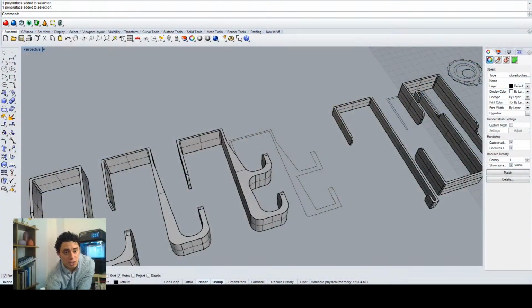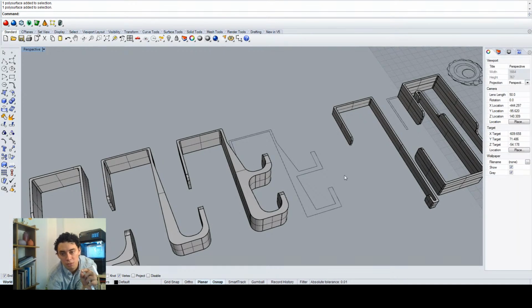So anyways, I started prototyping with it, saying how can I change this part? As I said, understanding what my requirements and my constraints were, and keeping that same door thickness constant, but allowing myself a little bit more beef, a little bit more material here in the part, so that I was able to actually strengthen the part and ultimately benefit from the structure that the door itself is giving me, right? So the door is already beefing up my part. I added this little detail that was just for me, to remove a little bit of material, maybe some of the print time.